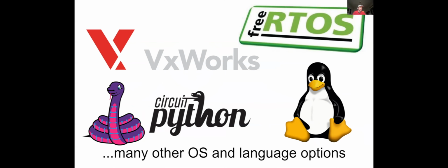And other options are a real-time operating system, which allows you to do things in real time. So if you have some sort of requirement, maybe you're doing some laser communications, and as soon as you get the first pulse, you need to send a pulse back, then you would want to use a real-time operating system because it enables you to interrupt and go directly to that other task because it has a super high priority to come in.